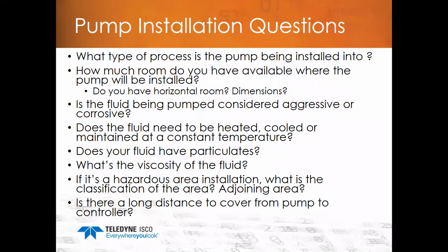Here's one you should be pretty familiar with. Does your fluid have particulates? We just talked about what large particulates do to the inside of a syringe pump cylinder. This question directly goes to that. Right off of that, when you're talking about the fluid that you're pumping, what's the viscosity? Is it thick like mud? Is it very thin like water, or is it somewhere in between? You want to know that because it's going to affect the type and style of pump that you choose and the types of applications you put it in.